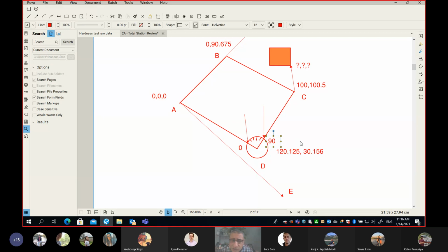So again, you can take any two readings, or maybe you can set the first reading to 0, which means the second reading will be 90. My point here is, let's go back to our first example and our first reading. I'm asking you, does a 10 by itself have any meaning? Let's say you got your total station, you level it, center it, you shoot to point A, and you got 10. Does the 10 itself have any meaning?